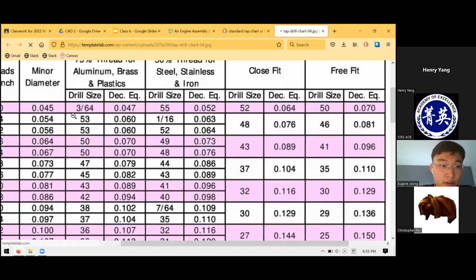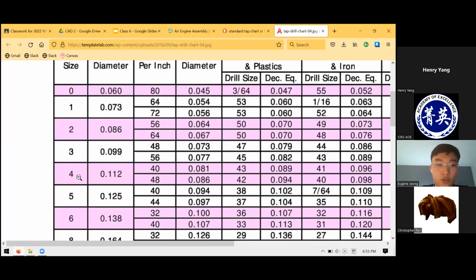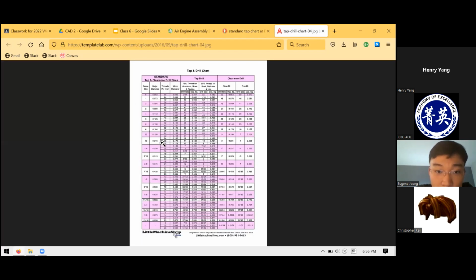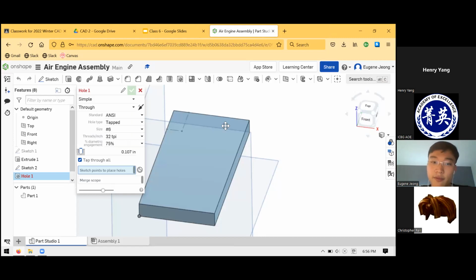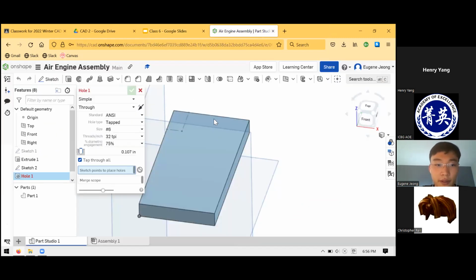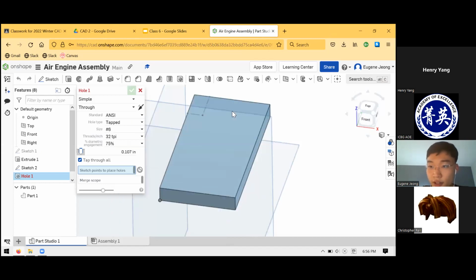These will tell you that for a screw size 10-32, the threaded diameter corresponds to 0.159. So you can use a chart like this. I know that 0.159 is greater than 0.125, so it makes sense to me that the first part of the hole is going to be deeper than that part. So I can just do this in 2 features.